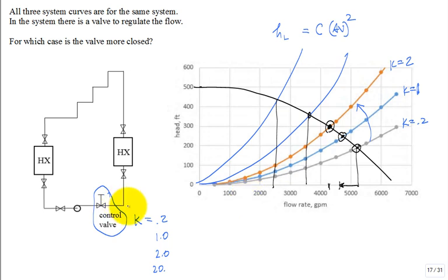This is the way you used to control the system, because the motor was fixed RPM. And so the motor, you just turned the motor on, it ran happily at 3,600 or 1,800 RPM, and that was it. A little bit of slip, so it wasn't a perfect 3,600, it was 3,520 or something. But they would like to run at that same speed.